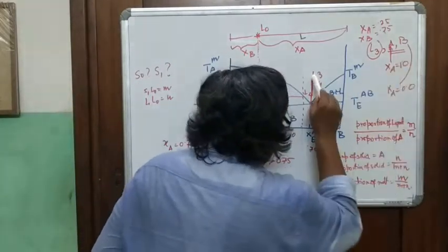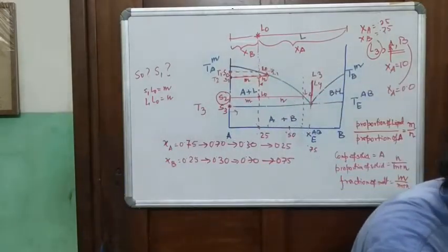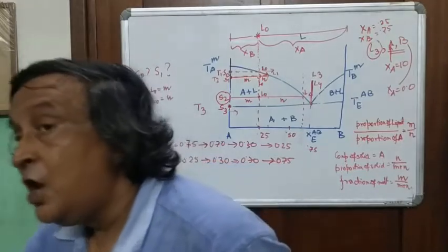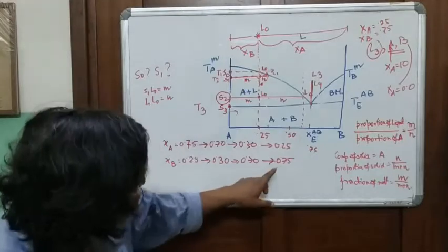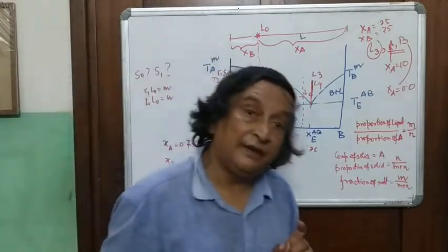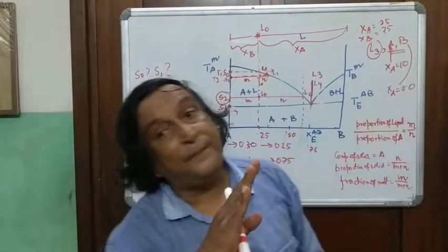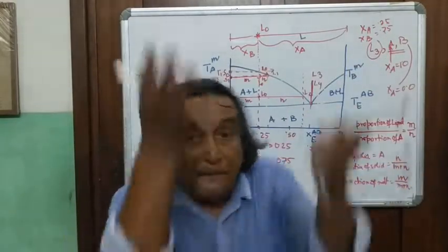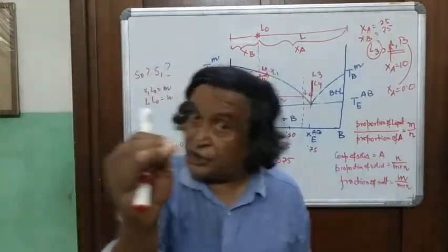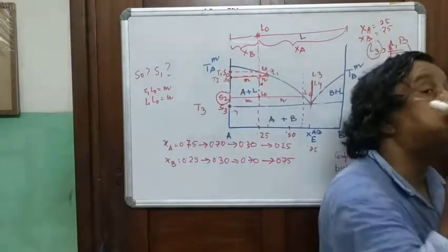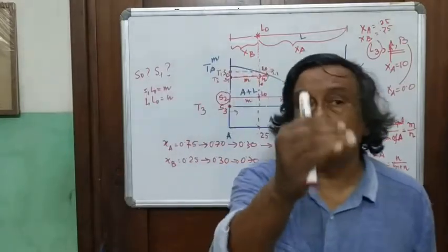At the eutectic, pure A crystal and pure B crystal will precipitate from the melt in the proportion of XA and XB, so that the composition of the melt will not change, but the proportion of the melt will change. That is a very important point.